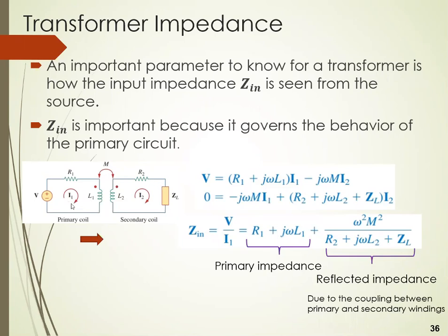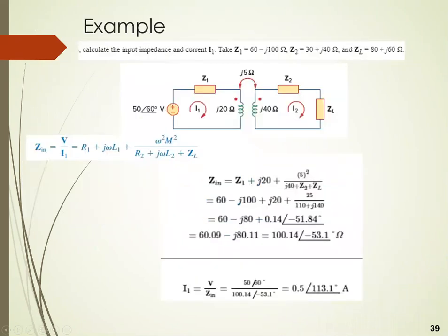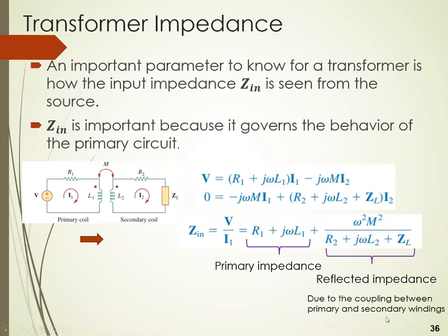So on the primary side, I1 is entering the current on the dotted side. So when I1 enters the primary on the dotted side, it's going to induce a voltage positive at the prime on the dotted side, negative on the undotted side.